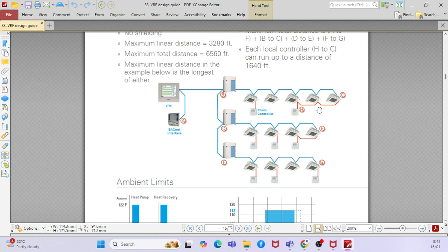Delta T. When you go with the VRF system or split unit, you have to select the outdoor unit, right? The ambient temperature you have to enter. There is an option to enter the ambient temperature, and also there is an option to enter the refrigerant pipeline.